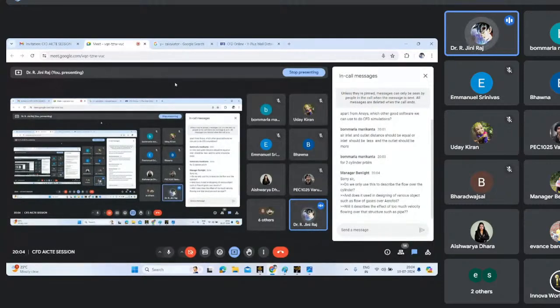If you want gases to flow over a cylinder, you have to change the fluid in the fluid database. That database I showed, right? Initially it is air, but I changed that to water. For some gases, you have to choose from that database. If you want to add your own fluid, that is somewhat difficult; there is a format, and you have to provide the details accordingly.